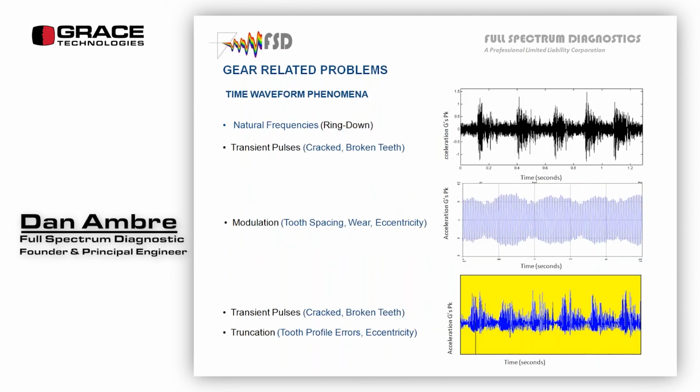Here is a series of time waveforms, and what you're seeing is a broken tooth in the top case, and it's been running for years, actually decades. I originally looked at this in 1996, I think, 1995, something like that, and it's still running. So it thumps, and every revolution of the gear, there's a crack, or a missing tooth or something in there that is pulsing. So it'll ring it, and it'll ring down like you're ringing a bell, and you'll get a very unique look.